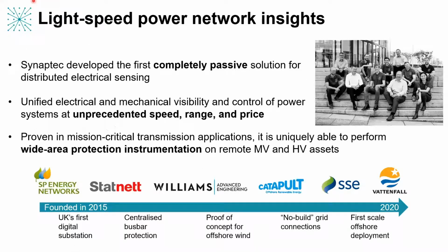So Synaptec is an instrumentation company. We're based in Glasgow in Scotland, and what we've done is we commercialized for the first time a distributed electrical sensing technology. What this means is that we're able to use the existing fiber optic, which is embedded already in, for example, the underground cables or subsea cables offshore, or in the optical ground wire in overhead lines.